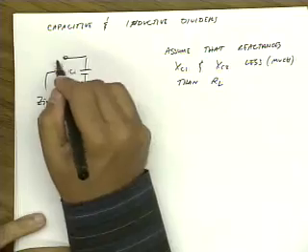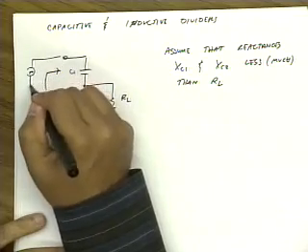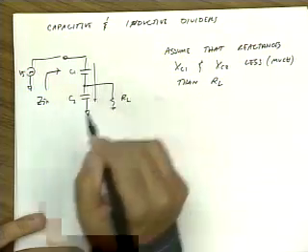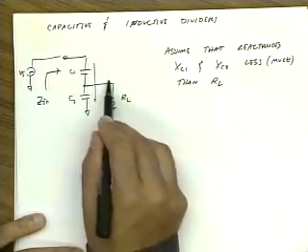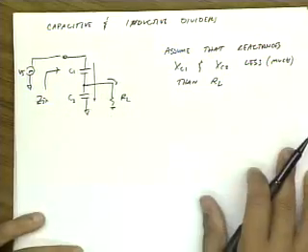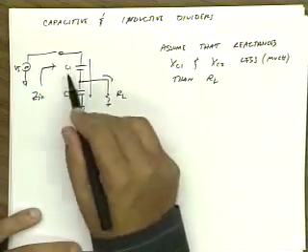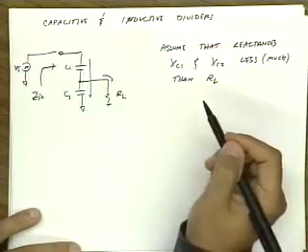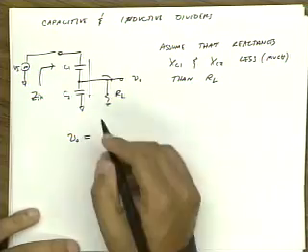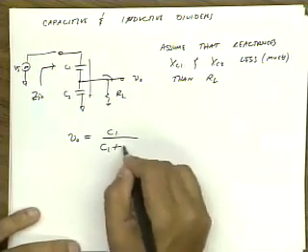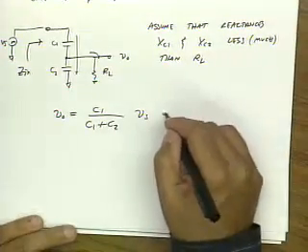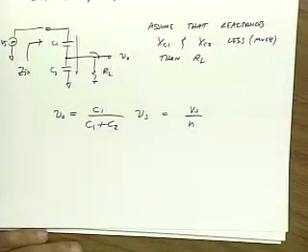That means that if I put in a voltage source here, most of the current actually will flow through here. Some small part of it will go through here, but just to make the analysis very simple, let's neglect that. Well, if that's the case, then this is simply a capacitive voltage divider, right? So if I call this Vout, Vout is equal to C1 over C1 plus C2 Vs, right? And I can say that this is Vs over N.